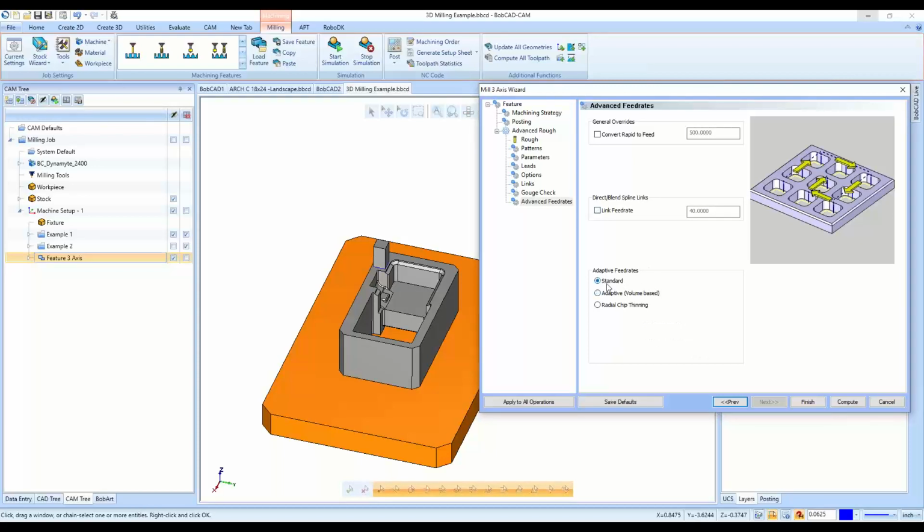Here is our standard where we have our 3-axis standard milling feed rate. We have some adaptive options here in the 3-axis Pro, where we can set a minimum and a maximum feed rate. For example, when the tool gets into larger material at a time, like into these corners, the software can calculate how slow the tool needs to move to keep a constant chip load. And that can reduce chattering at the machine, for example. So at every single move, we just let the software work for us and set the feed rate, slow it down so that it doesn't chatter into those corners.